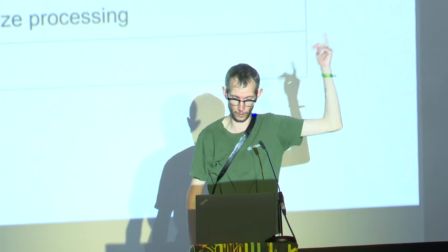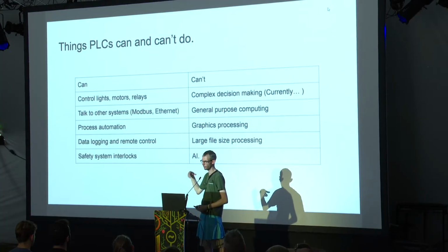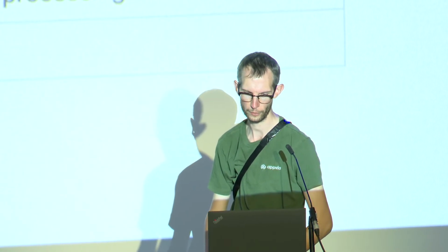And the way that the clock works this time is that you can control it from a web app now, and that converts to Modbus, and the Modbus gateway is on my server in the cloud, and then talks back to the PLC and says, set these coils that correspond to these bits of I/O bus on or off, and that makes the display work.